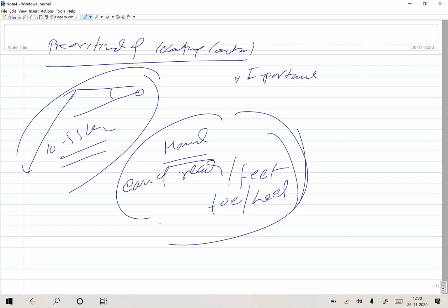And when we have identified the most preferred location for locating the control, we need to see the importance. Something which is most important will be located in the most preferred area. Second is the frequency of use: something which is very frequently used or rarely used. Accordingly, the controls will be located. Then there is the functional type. The controls which are of a similar type will be located at the same place. There are controls for increasing the speed or decreasing the speed.